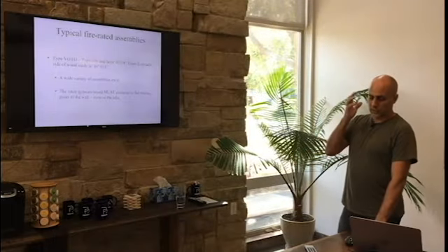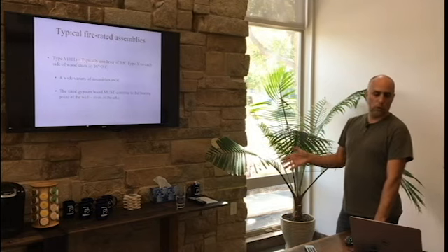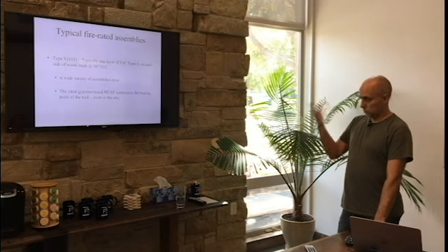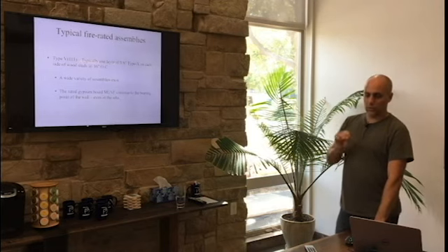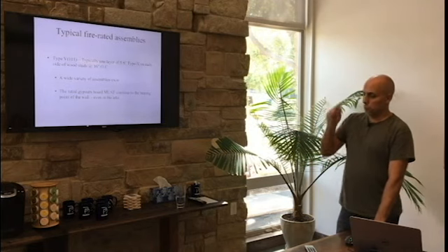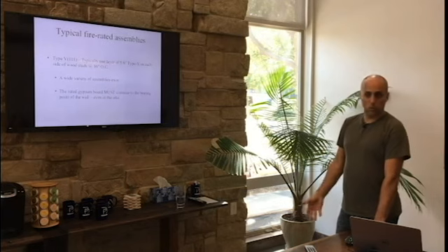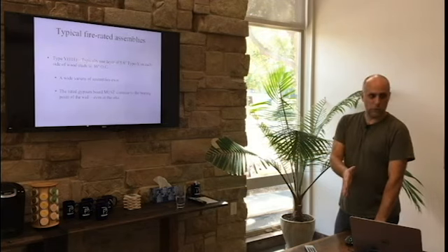There are assemblies that say any classified 5/8 inch thick type X gypsum board, 1 layer each side, is a 1 hour wall. If it says any classified board, that means any board that UL has considered classified, which is X, which is rated. You could use any single one, anything you want. But there are also those that say you must use just this board for a wall. Like you have one choice. Well, if you choose to use that assembly, you must use that gypsum board.